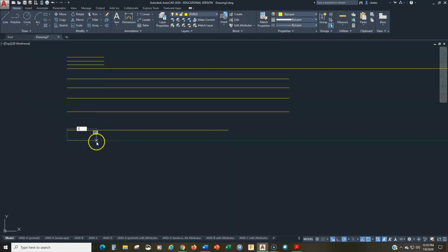Or I could do 2 foot 6. Now, how am I going to get the half in there? If I do a space, we know that that's going to enter that. So I don't want to put a space in there because that'll just enter the command and I won't have the half in there. So if I can't do a space, what could I do? I could do a dash 1, 2, 1/2. Okay. Do I need the double quotes? No. All right. So let's do that.